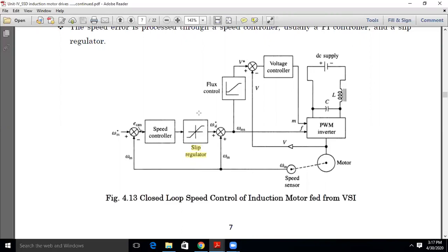It is not essential to control the firing angle, duty cycle and time period of the inverter every time for the required speed. This closed loop control makes sure that the required speed at which the induction motor needs to operate will be set as the reference automatically. The entire closed loop function adjusts the speed of the induction motor.